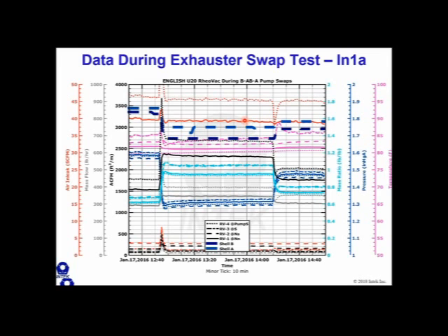What you do see is that we are able to reduce the condenser pressure by running two vacuum pumps. And so this is probably very common for you all at your operating plants. When you suspect an air in leakage problem, the very first thing you do is try not to waste money. So turn on the vacuum pump. Turn on your backup vacuum pump.